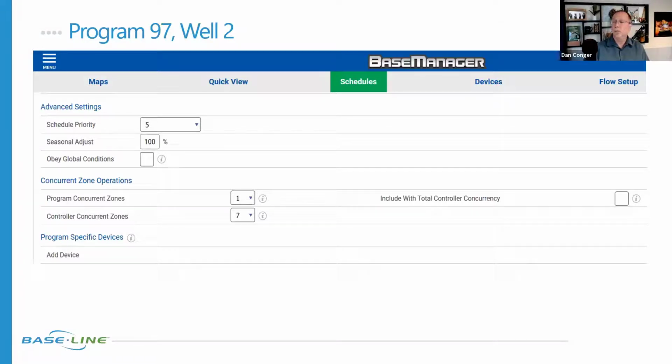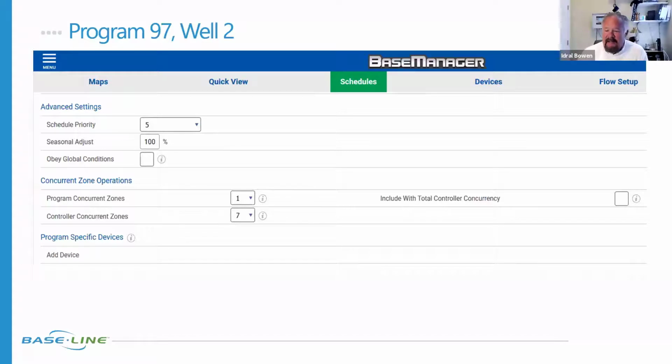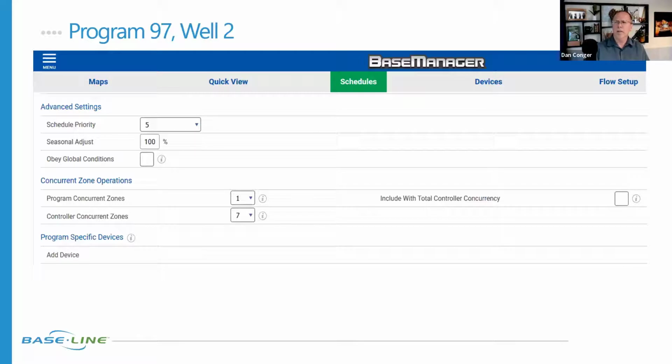Well, that's the point. That's actually a situation we had out there where they turn things off and they turn the dial to off. And I had to coach him: if you want to turn off irrigation, please use the rain shutdown so we can still continue to fill the cistern. So it was just a little training on their part. They had to learn, don't turn the controller off, do a rain stop, and then we can still continue to maintain tank level. I could see a rain event as a great time to catch up on filling up that cistern, right? Because after the rain event, let's have that cistern topped off and ready to go for irrigation whenever the irrigation is going to come back up again.